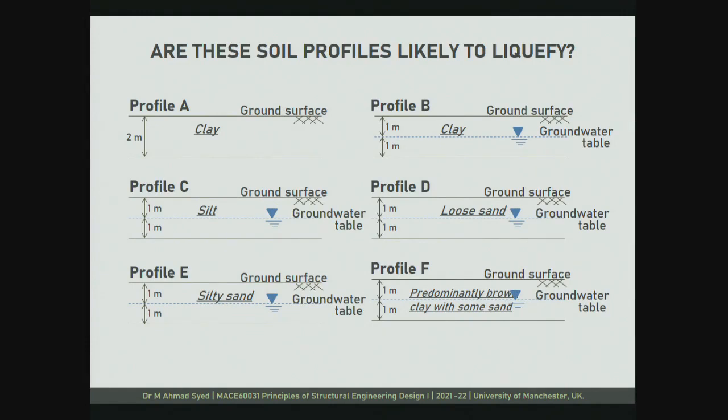So yes, if you recall the Mohr-Coulomb failure criterion, tau is equal to c prime plus sigma tan phi prime. So cohesion will always be there, that is one thing. What about the shape of clay particles? Clays are usually platy particles, but here what we are talking about is a granular soil mass, which eases these rolling and sliding phenomena. Because of the shape of these clay particles, it is very unlikely that clay will be liquefied on its own.